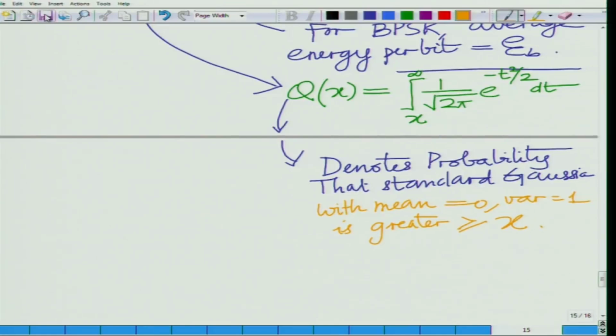Okay. So, in this module we explored one of the simplest, most popular and robust schemes for digital modulation, that is BPSK, binary phase shift keying, which uses two cosine waveforms shifted from each other by a phase of pi. Therefore, it is known as binary phase shift keying. We have seen the transmitted waveform, we have seen the optimal processing at the receiver, which is matched filtering, and also seen the resulting probability of bit error.